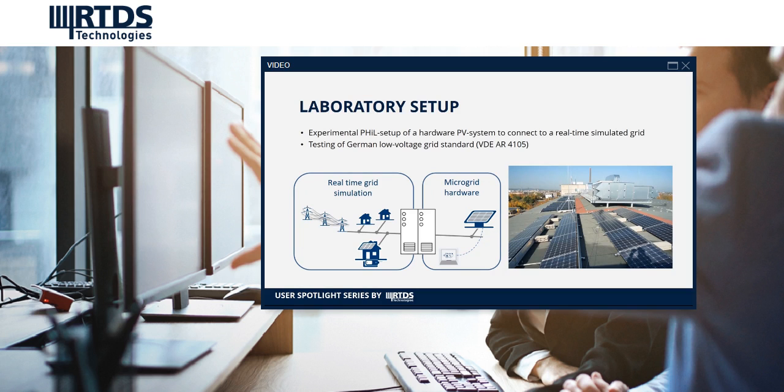The advantage of this setup is much deeper testing possibilities for the hardware with less expense than we would have with a real grid. I can perform testing of the grid standards, for example the German low voltage standard VDE AR 4105, which regulates how a PV converter has to behave in terms of over or under frequency, voltage sag or swell, blackout, fault ride through, etc.